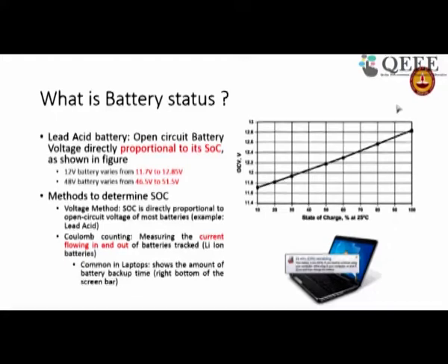A laptop has a lithium battery, and with a lithium battery you can't measure open circuit voltage this way. So it actually monitors how much time you charge and how much has been discharged in total, and keeps giving you updates, and then gives you a warning saying now it is 85%, or 21 minutes, 10% remaining, 90% has gone. It can go on, but it will start damaging the battery.